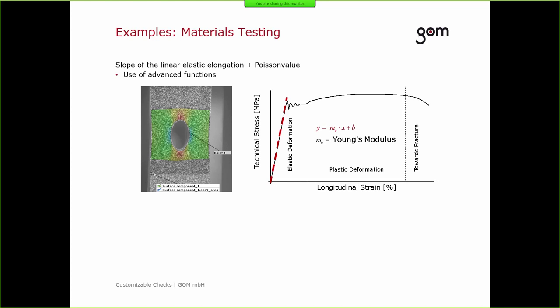It's derived from tensile tests often, and here you have to define an area which an average is made for the elongation in the y direction, this part, and also the stresses shall be calculated here to use this stress strain curve to fit a line in. So as mentioned, I will show you how to choose these areas, make your checks on these areas, and also how to calculate your Young's modulus from the stress and strain curve.